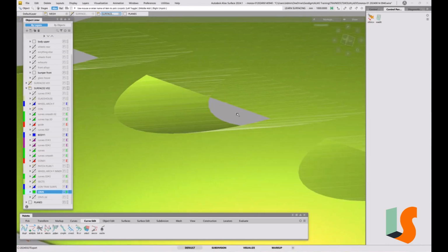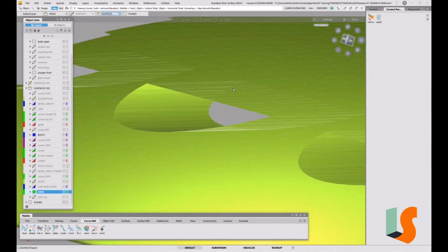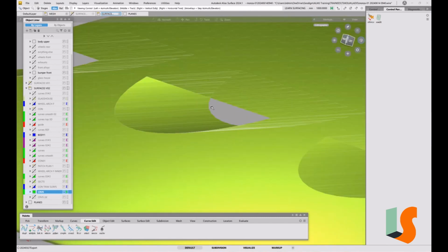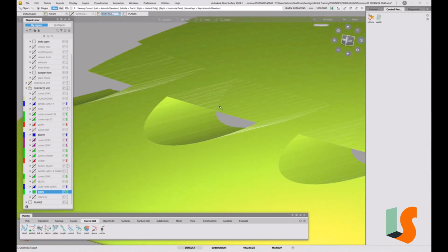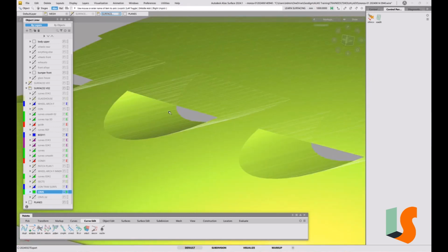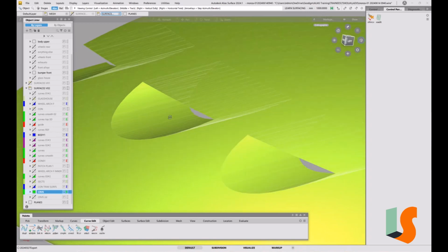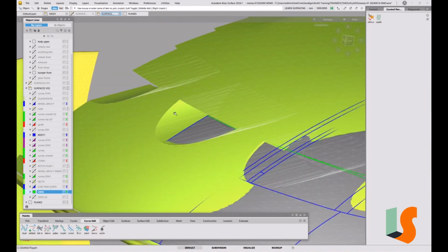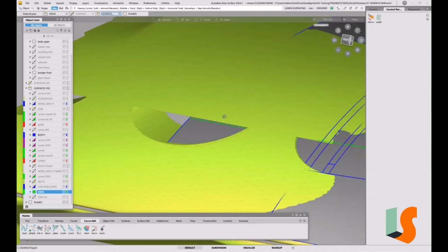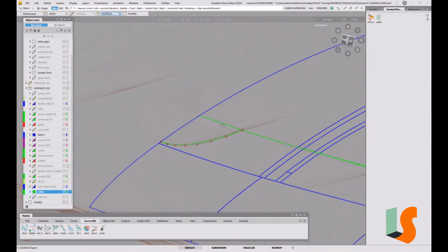That means either we move that block surface downwards until the fillet looks right, or we could angle the block surface so it's not quite as sharp as that when we put the fillet in. I'm not sure what we're going to get, and therefore I'm going to use history as much as possible so that we can change the angles of these surfaces if we need to. Well, we inevitably will need to, I'm sure.